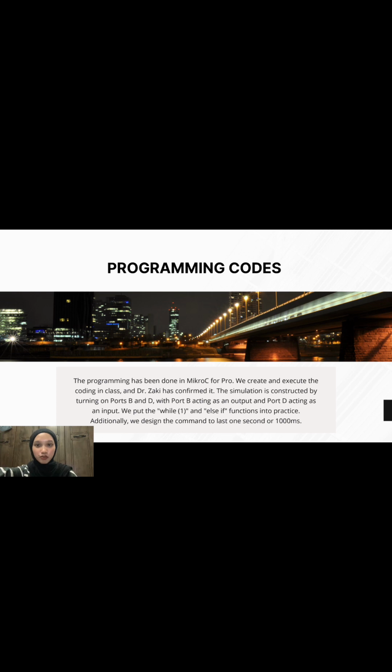Next, I will explain about the programming codes. As we know, we have created a simulation for the programming codes using mikroC PRO for PIC. We created and executed the coding in class with Dr. Zaki, and he has confirmed it. The simulation is controlled by turning on port B and port D, where port B we use for the output and port D we use as an input.